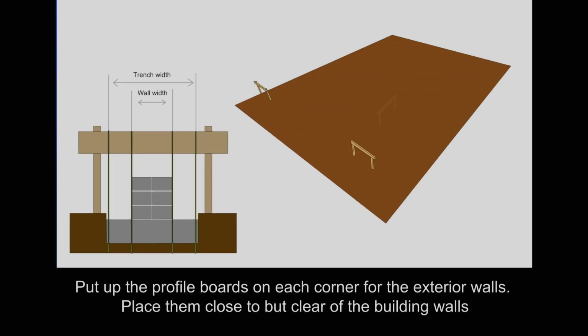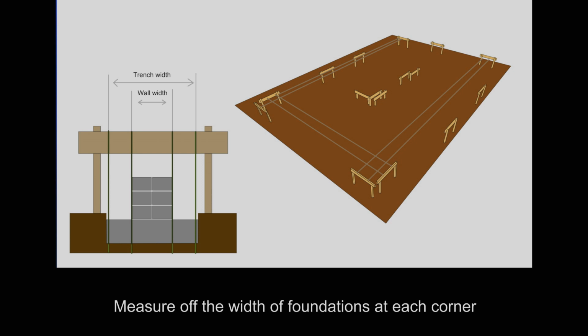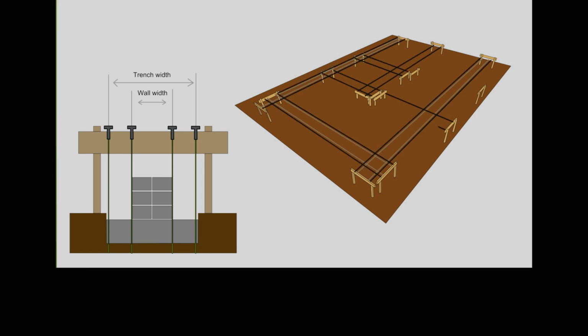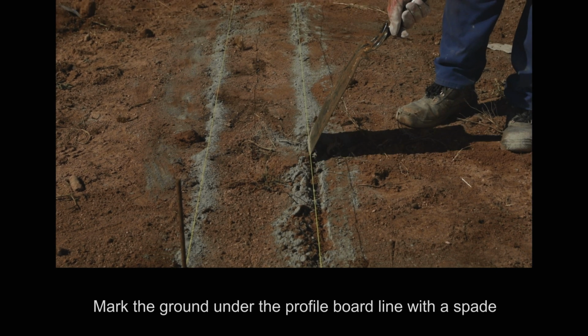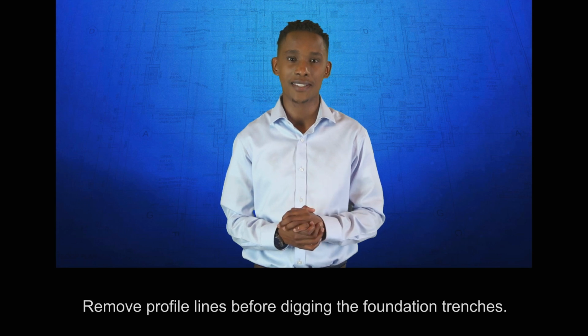Put up the profile boards on each corner for the exterior walls. Place them close to but clear of the building walls. Put out profile boards for interior walls. Measure off the width of foundations at each corner. Knock a nail into the top of each profile board for each side of the foundation and put up profile lines. Mark the ground under the profile board line with a spade. Remove profile lines before digging the foundation trenches.